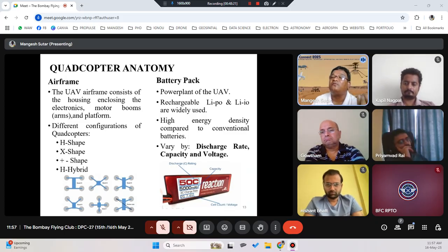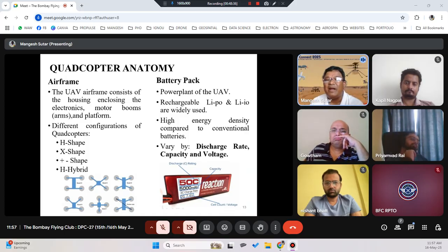but they cannot actually power drones, because a drone will draw a lot of current. Like we talked about, something like 24 or 25 amperes of current. Okay, so it requires a lot of power and energy. That's why we always use lithium polymer or lithium ion batteries. If you look at the batteries, there are two things which you need to see.